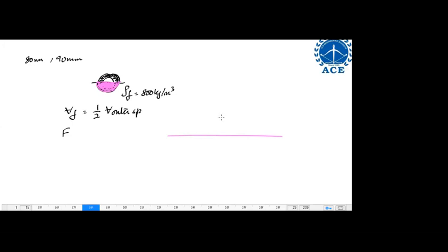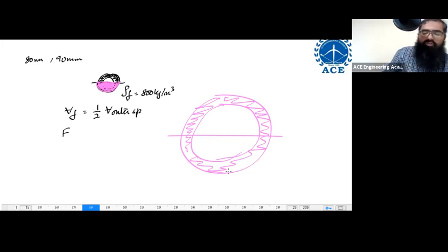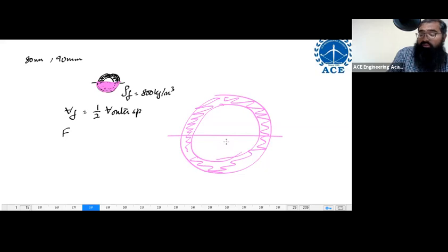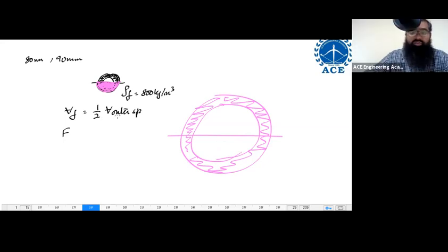Okay. Imagine, madam, that the diagram over there was very small. Now try to imagine like this. The sphere is only this portion. But tell me, the volume of fluid displaced is how much? This portion, where my cursor is, is it having oil or not? No, it's not having oil. That means this volume also has been displaced. So the volume displaced is equal to half the volume of the outer sphere.